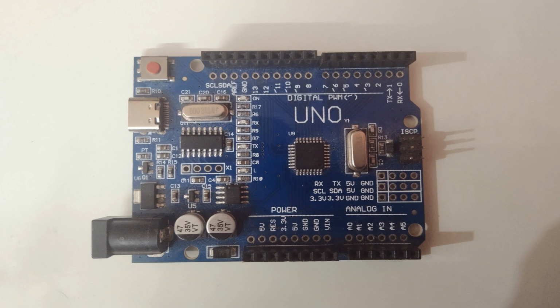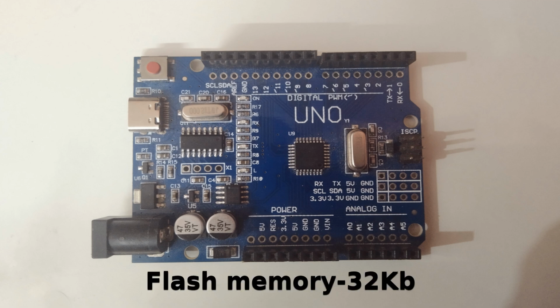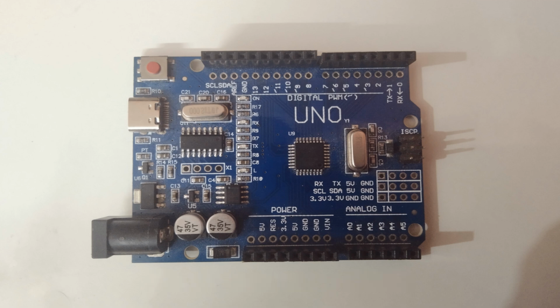Next we have the analog input pins, which are 6 pins, from A0 to A5, and the DC current per input/output pin is 20 milliamps. It has flash memory of about 32 kilobytes, of which 0.5 kilobytes is used by the bootloader, SRAM of 2 KB, and EEPROM of 1 KB, and it works at a speed of 16 megahertz. It also has a built-in LED on pin number 13.